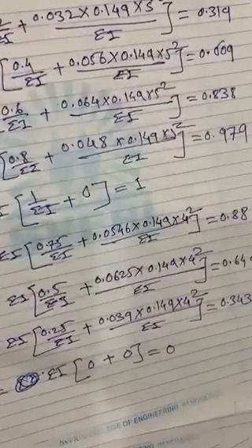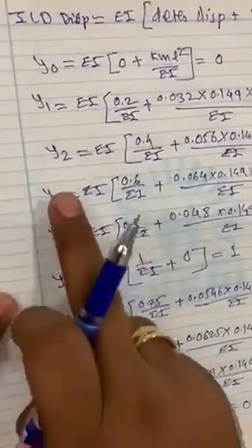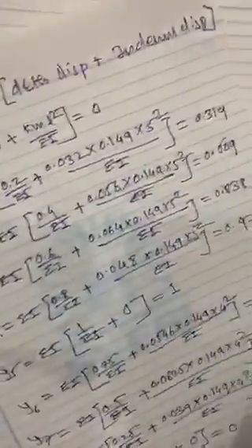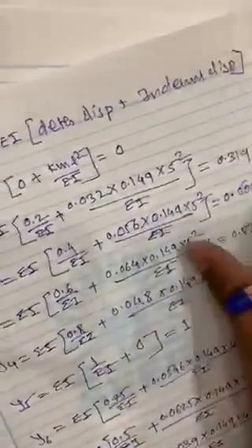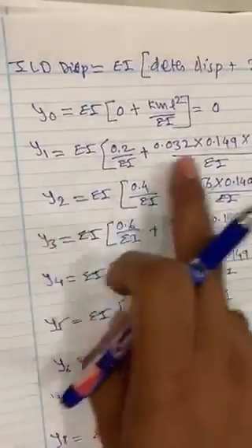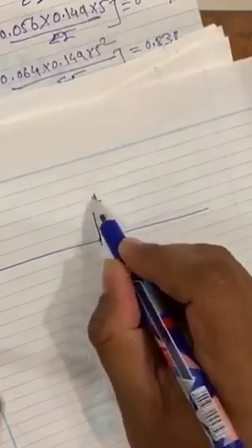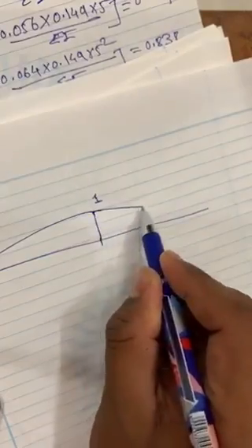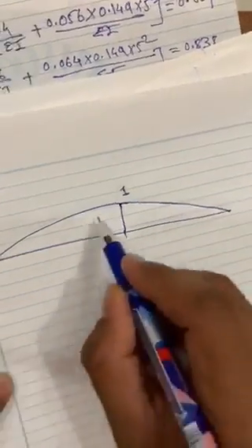So this way we got all the values, from Y1, Y2, Y3, Y4, Y5, Y6 to Y8, Y9, and this is an addition. The total displacement will be more than the determinate value, so the curve will come out convex. You will have to draw 1 for RB, and this will come as a convex type of curve because there is an addition.